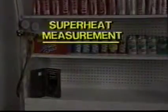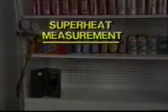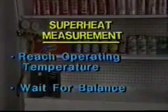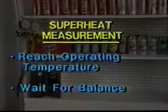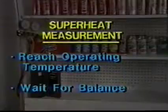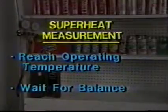Before discussing the details of superheat measurement and adjustment, we must keep in mind the need for letting the system reach a balanced condition. It takes some amount of time for a system to stabilize after a superheat adjustment is made. System balance will normally take place in about 15 minutes.